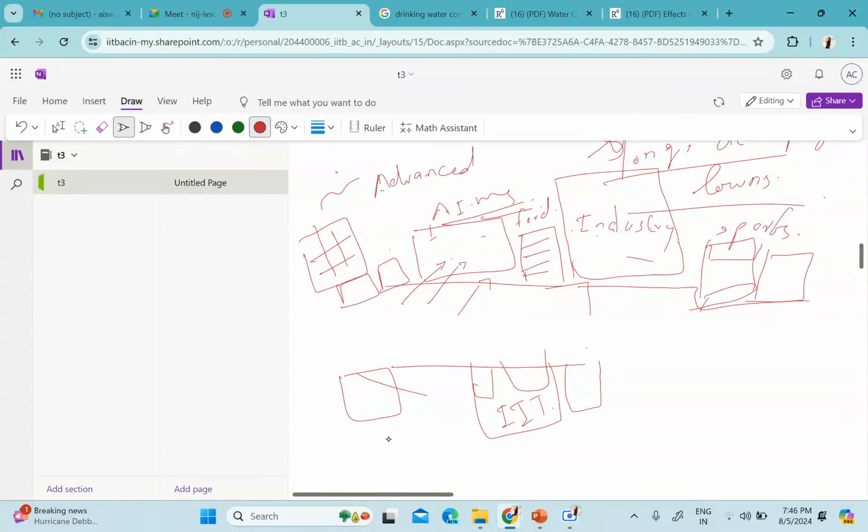It is young but developing, and we know there will be huge population growth in future years. For these types of young and developing cities, where we are sure a huge population is going to come, we apply the geometric increment method.